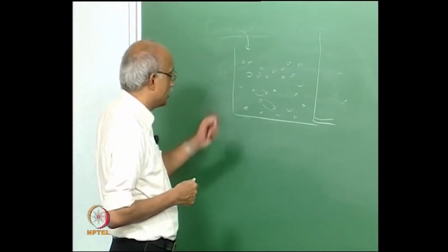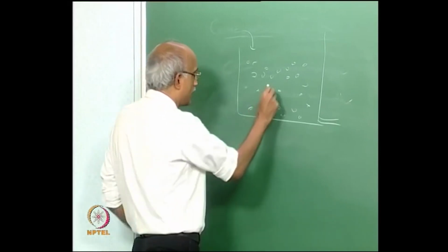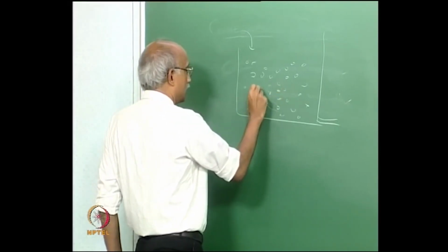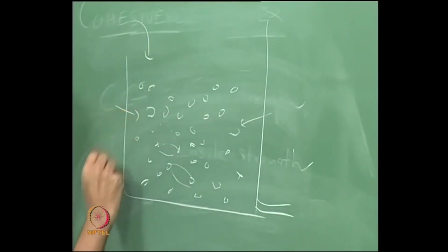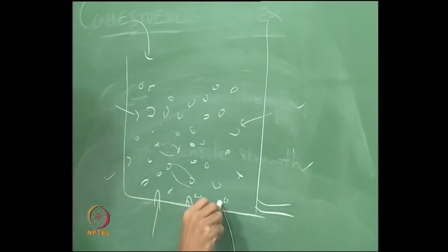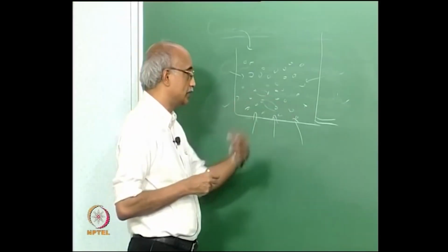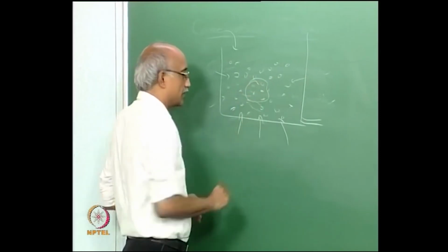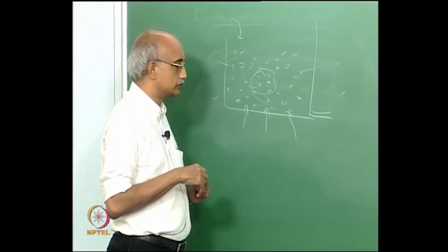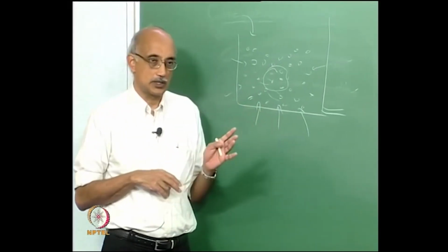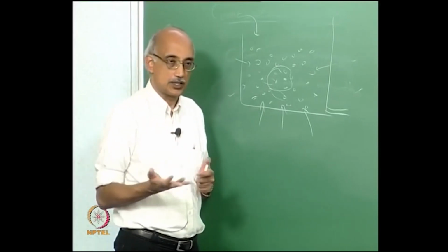The situation here though is a little complex, because when you have a highly densely packed material here, for your experimentation, the probes can only be stationed towards the boundaries, otherwise they become an intrusive effect themselves. So experimentation is actually very difficult in the bulk of the particulate media that are traveling through the system. It is very difficult to do experiments on the interior of this fluid, but that is really the only way you can characterize the flowability in an experimental fashion.